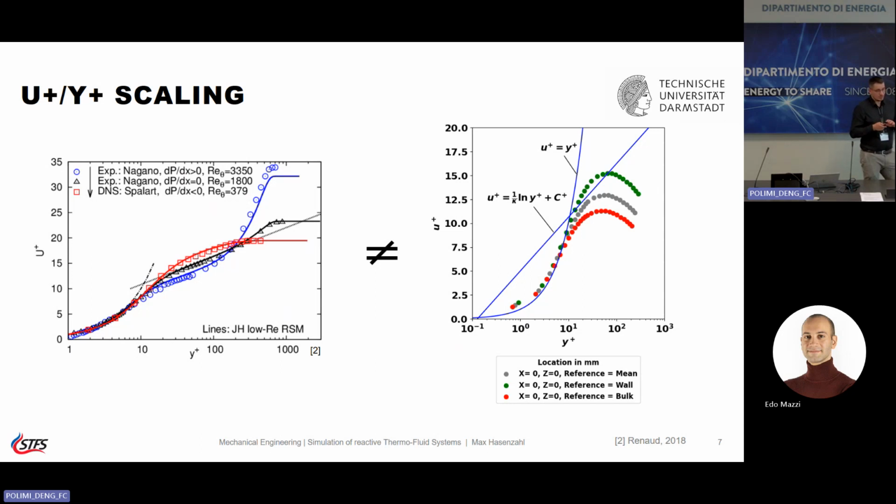And it also means if you look at values of this reported in literature, people may use different scaling. Some use the scaling at the wall, some use bulk velocity. I've seen people assume adiabatic compression to do their scaling. So this doesn't change the fact that you don't have a log-law region, but it does change where you are. And if you make interpretations based on this about pressure gradient, I would advise to be cautious on this. Okay.